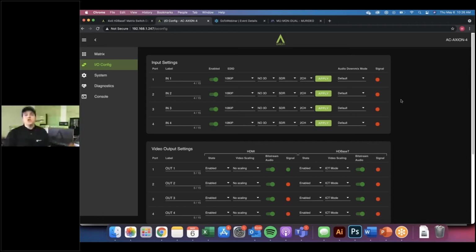And one of the biggest breakthroughs that we have for you is we've always given you EDID choices. And EDID is the signal that goes from a sink to a source, so the opposite direction, a TV to a gaming console, a TV to a Roku Ultra, a TV to an Apple 4K, and it tells them, hey, this is what I'm capable of doing. Well, with Axiom, you can now build your own EDID.